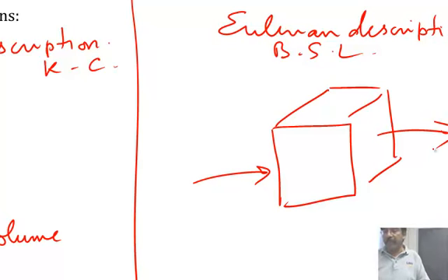Now, I'm studying flow in a pipe, in a chemical plant. I have a pipe that carries crude, and I want to know what the flow rate is, because I want to meter. I want to know how much crude I'm processing. So I'm putting a device, an orifice meter or a venturi meter, a device that measures the flow rate. And that is an Eulerian description, because I'm fixing the location and I'm observing what comes in and what goes out and counting how much material is going through that.